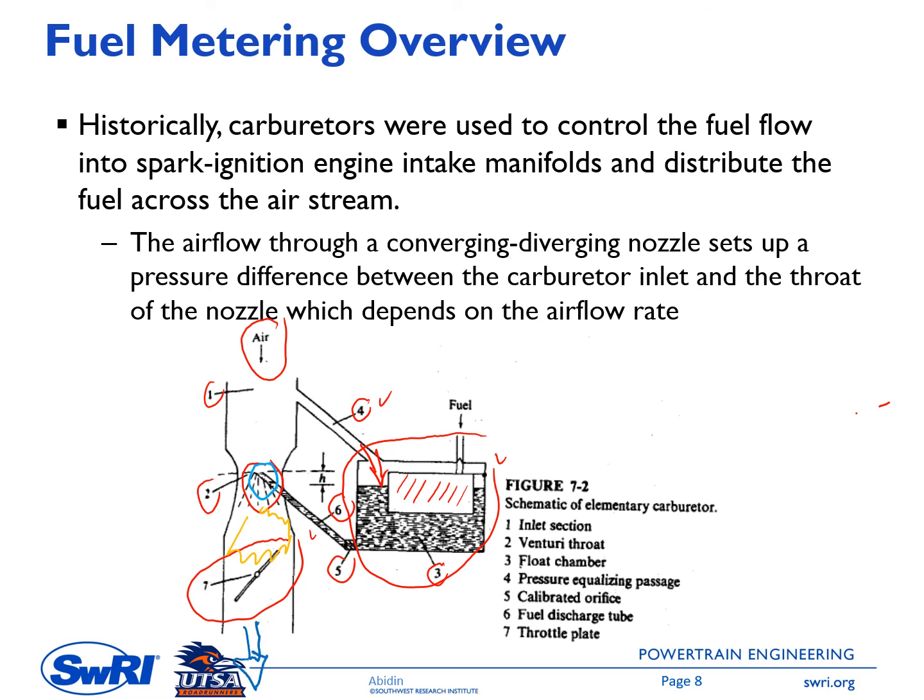As I mentioned, this throttle plate controls the amount of mixture flow. This is a simple flow control, so it's cheap, but there will be a decent pressure drop through this throttle plate, which is not good from the volumetric efficiency perspective.